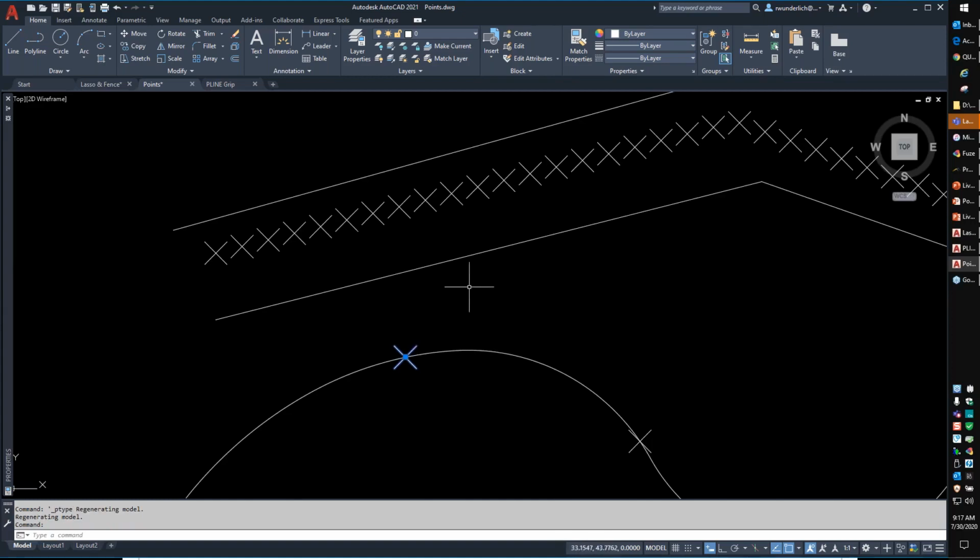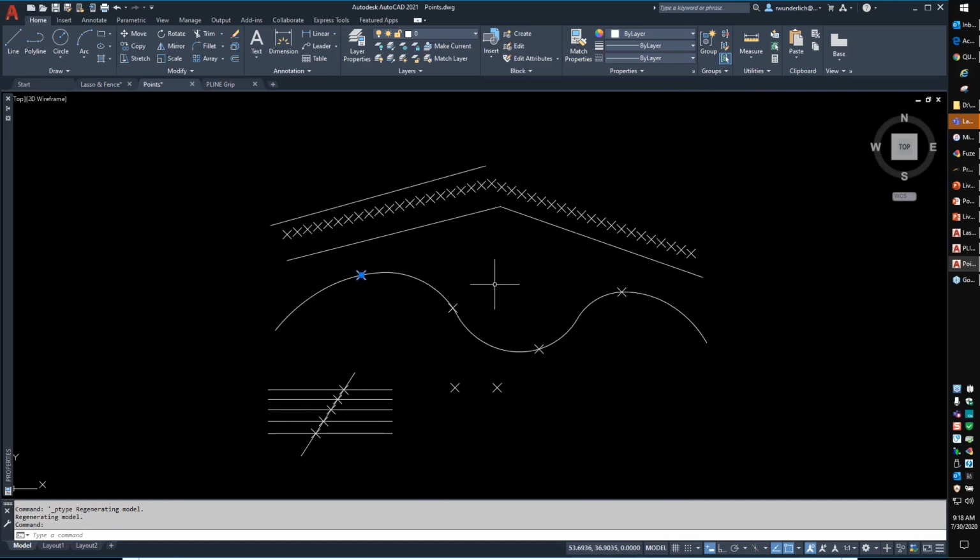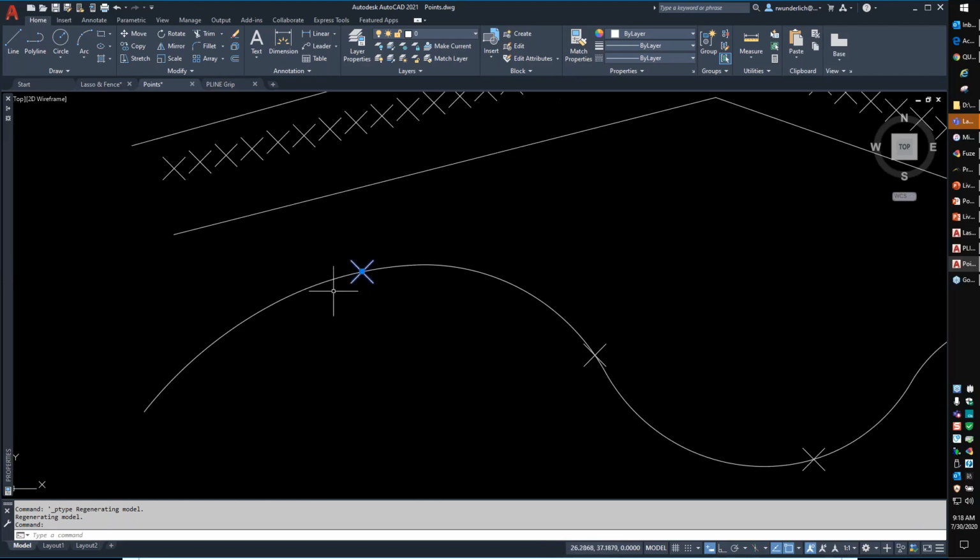If you simply want to get rid of the points, you can use Q select, the Q select command, and we will talk about, there's a resource center that we have on our IMAGINiT. Can you have two different style of points in the same drawing? No, you are only allowed to have one point style for the entire drawing. A lot of good questions with points, guys. Thank you. So if I want to select an individual point, I can do this.